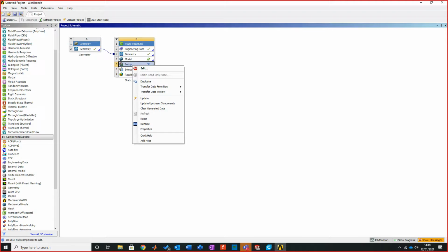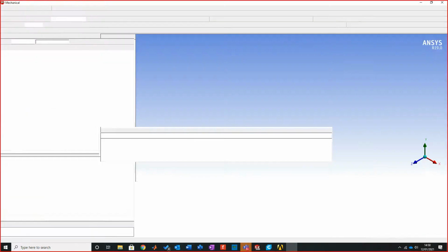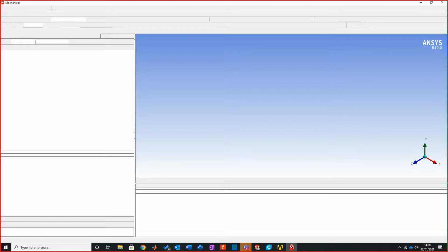And now, what this allows me to do is to go through ANSYS and use its absolutely phenomenal tools for meshing. And it allows me now to have that freedom of a tetrahedral for quadratic meshing. I can choose, as you know, your node, your edging. There's so much more freedom that I've got here, and this is what I meant. So you kind of let the little CAD system give you a recommendation, and then you run it through something serious like this.